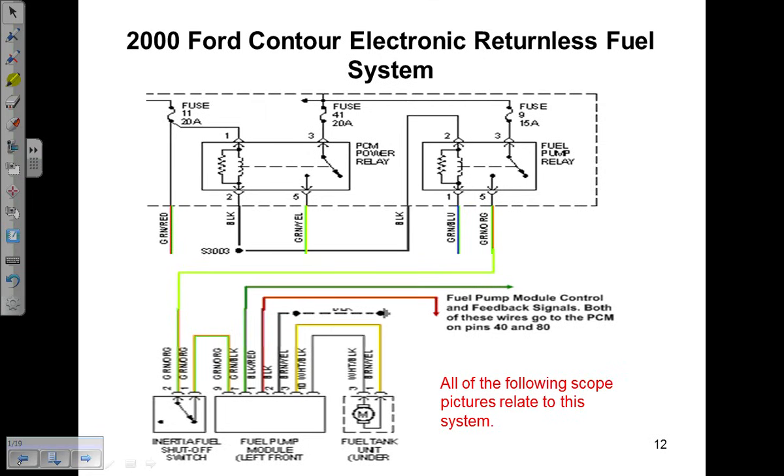All right, fuel pump electrical circuits. It's not just as simple in some cases as just a power and a ground, tech. You can have variable speed pumps. You can have resistors dropping voltage. You have to know how to read a wiring diagram. That's going to be key.